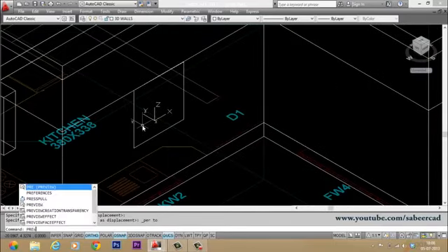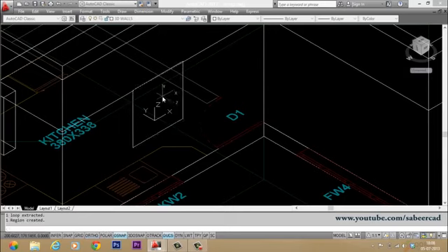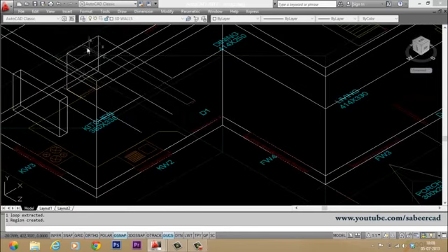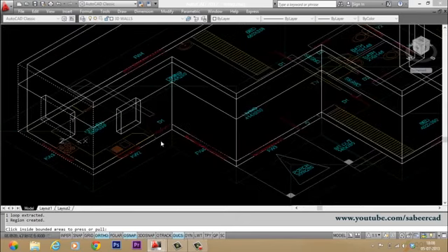Now you can give the press pull command. Type press. Just give an enter. Now you select the profile. Just click a point inside the profile. Then you drag to create a surface. Now you have pulled a surface. Now you have made a cutout there.